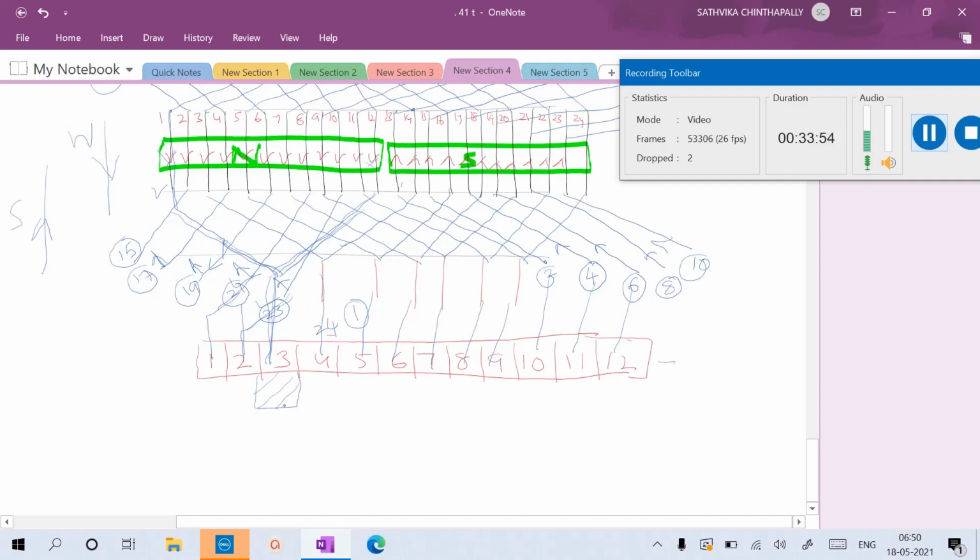You place one brush here, which you can indicate as plus. Now, where both currents are going in the upward direction, you can see the current direction is upward, and at the same time this direction is upward, so the 13th and 24th conductors are connected nearby to the 9th slot, you can see it. Here you connect the opposite brush, that is minus.